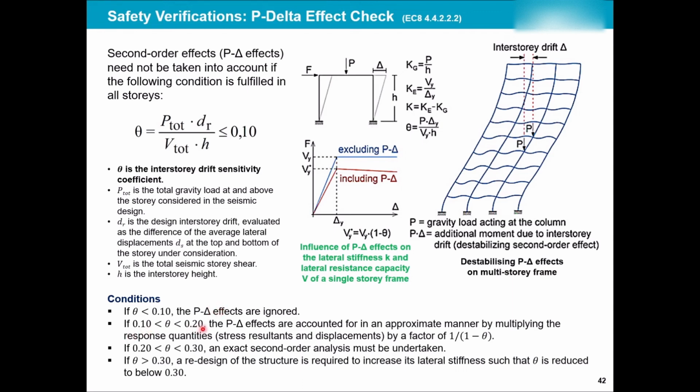But if it's between 10 and 20%, it gives you a magnification factor that you can apply and carry on the analysis. So it increases the displacements and the stresses that you have, so your sections will be a little bit stronger.